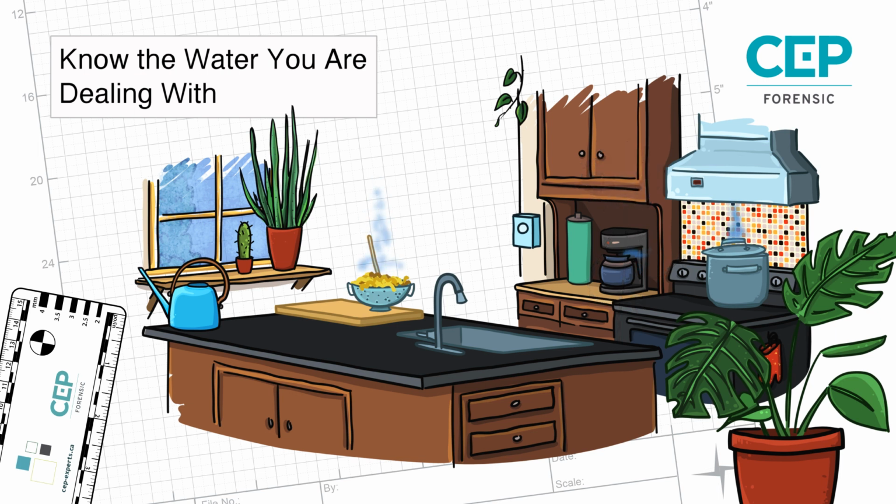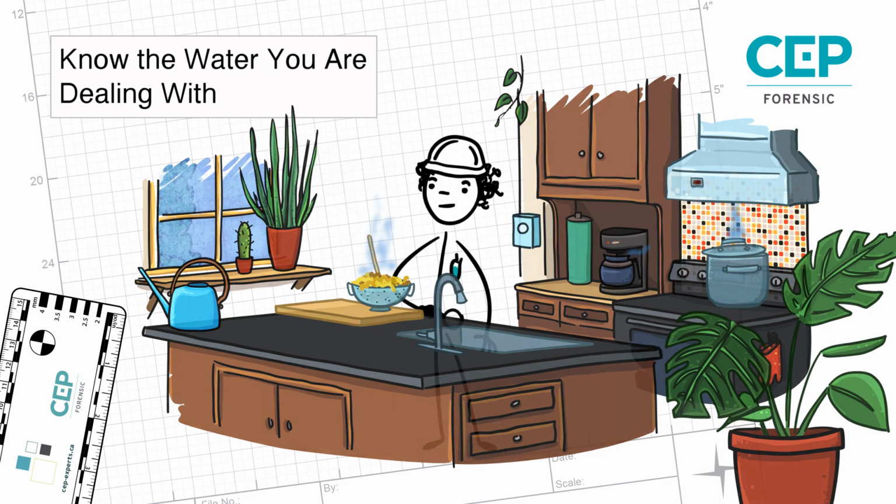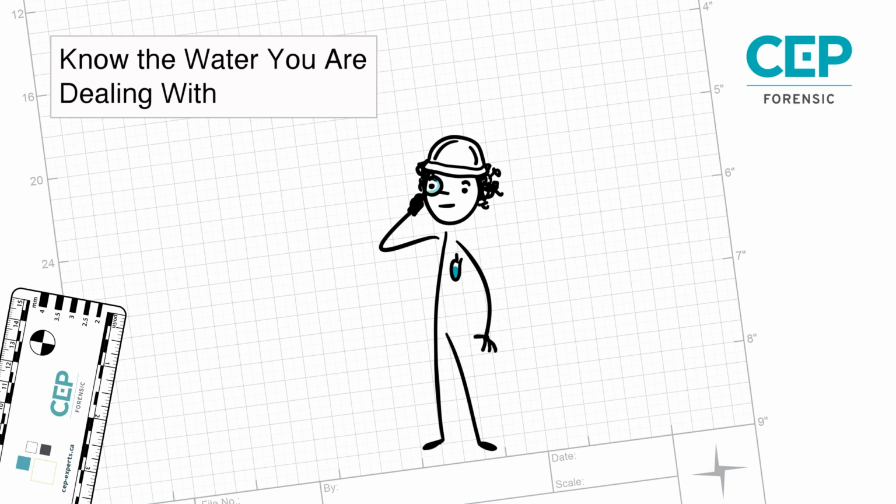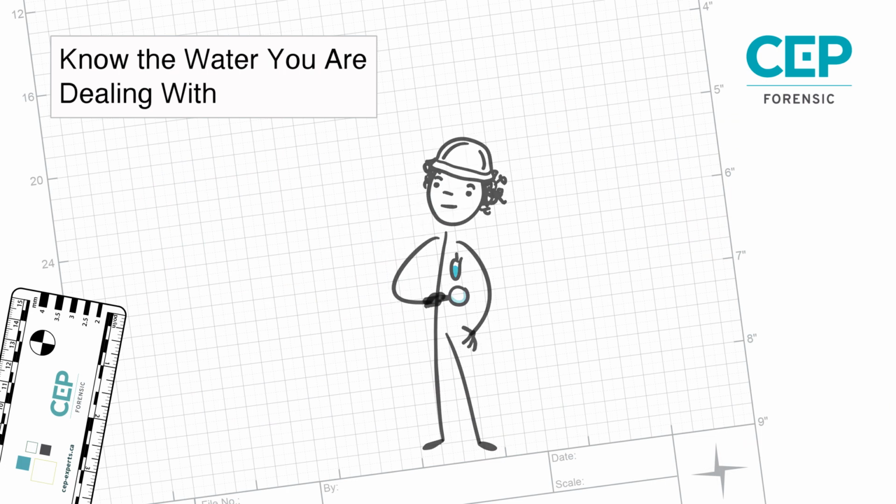When investigating a moisture-related loss, it is important to identify uncontrolled air leakage, thermal bridging, and poor humidity management. The principles of building science, construction materials and practices, and ventilation requirements must be well understood by the investigator to ensure the cause is accurately determined.